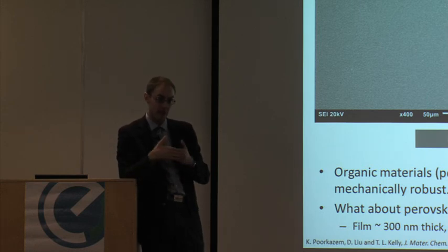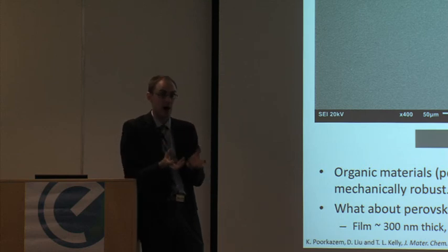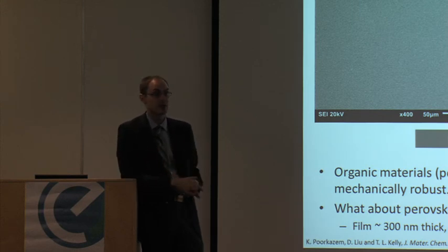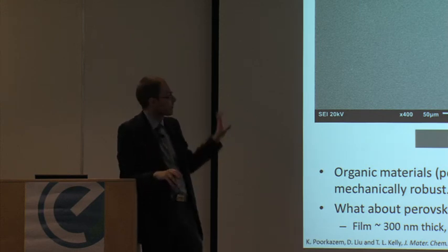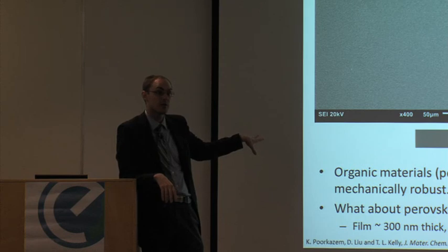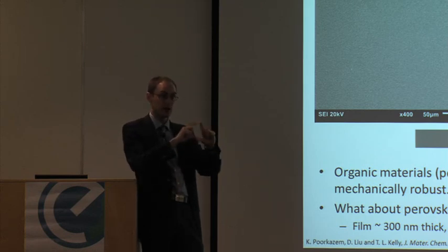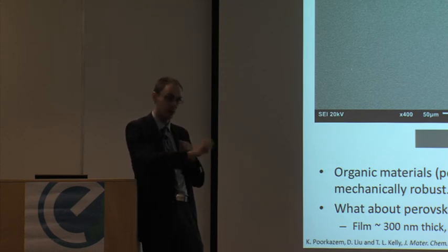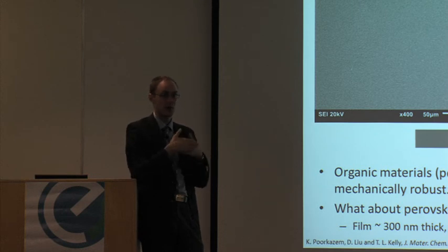And so you can make the film a little thicker because you've got that high surface area electron selective contact, so you can more effectively extract out your carriers. But in theory, as with Yang Yang's work or one of the recent papers from Los Alamos in Science, if you have a really good crystal, your charge carrier diffusion lengths are really, really long, and it hardly matters how thick you make that layer.